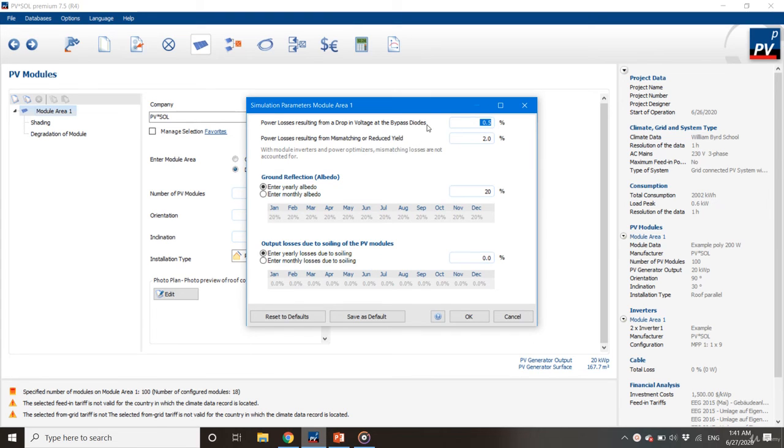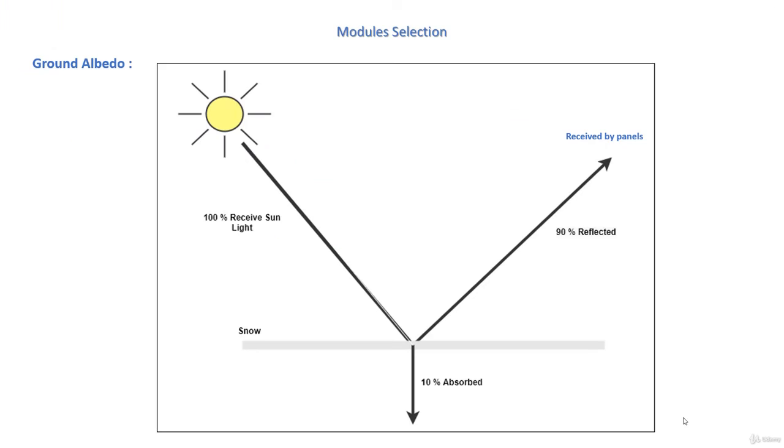If you have information about some losses, such as the losses caused by the voltage drop or bypass diodes, most times they could be ignored. When connecting different panels, the overall power from the two will usually not be the same as if they were at their peak, due to different MPPTs or maximum power point tracking of the two and different points of operation. The value is often from 1% to 5% at most.